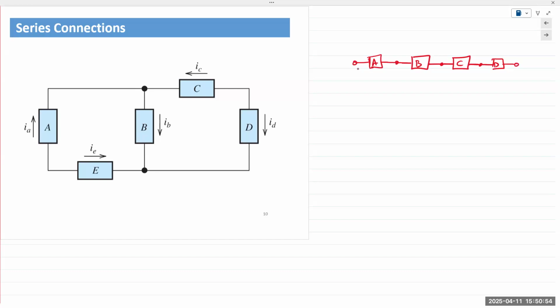So we can state all of them are in series. Technically, you could have 1,000, 100,000, a million, a billion, a trillion components all in series, as long as they only share one connection each, and each shared connection has no more than two elements connected to it.